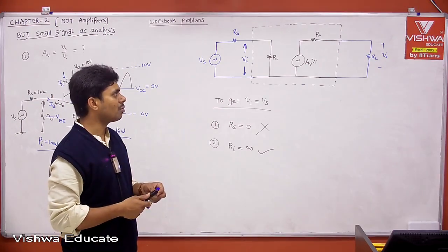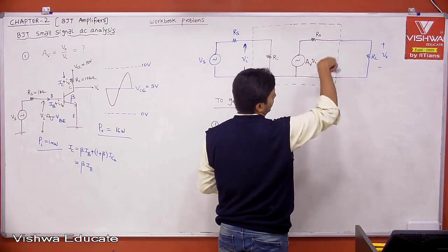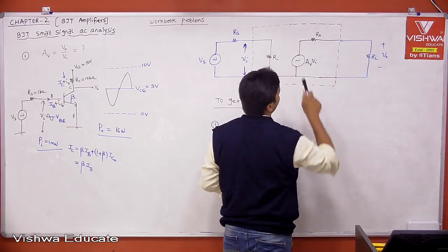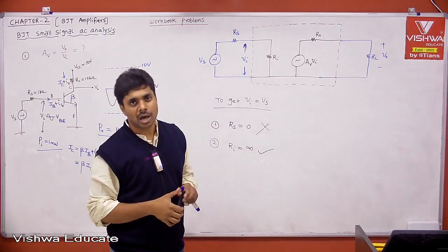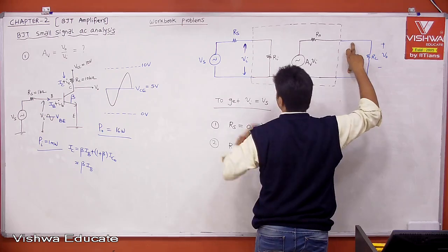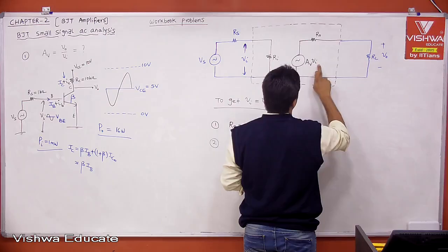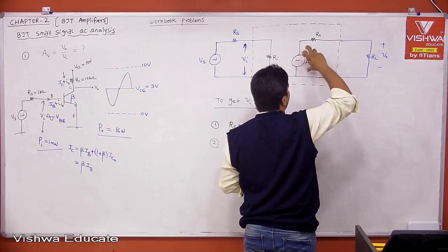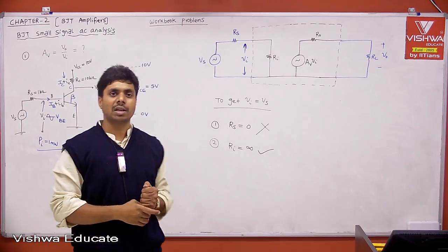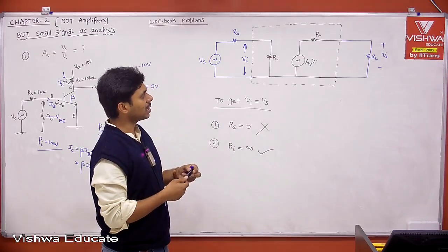Now let's come back to the output side. You may ask, how did I model this like this, right? Remember, your amplifier is the voltage source for your load. Then I told you this is R0. We know the R0 definition. What is the R0 definition? Exclude the load, the impedance seen into the output port when Vs is 0. When Vs is 0, Vi is 0. When Vi is 0, AV into Vi is 0. Short circuit. It is simply left with R0. That is R0, which satisfies the definition. And we already calculated that R0, so you can use it here. Therefore, I can represent it as a voltage source.